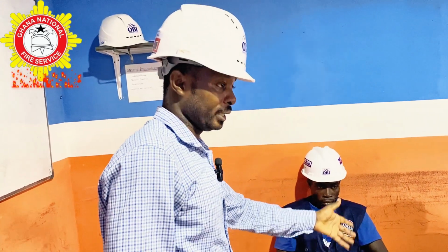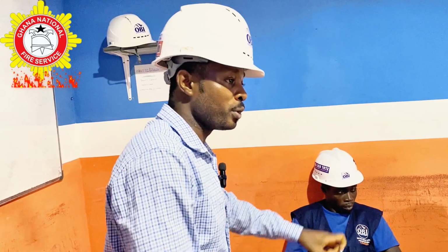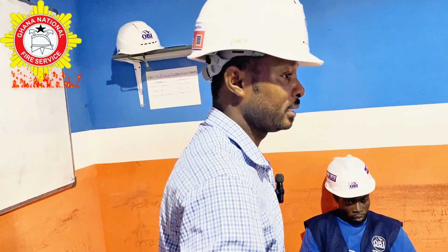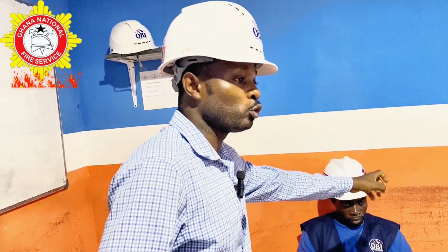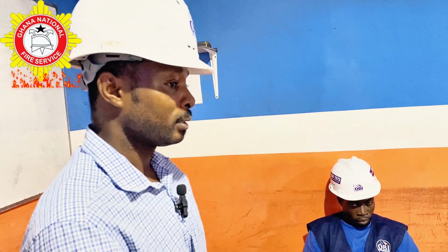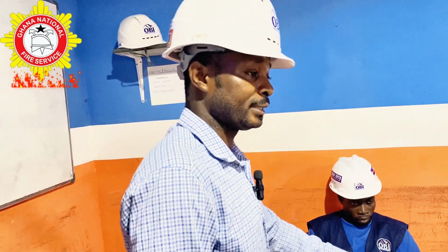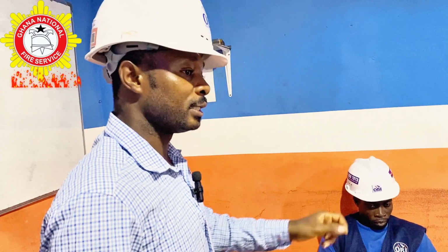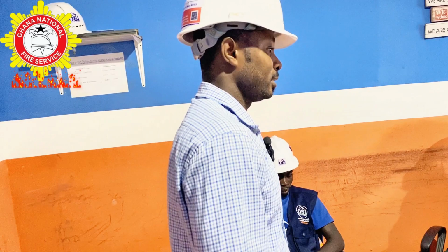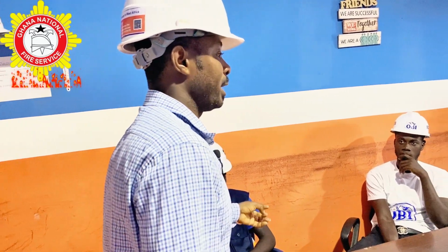Some are better than others, but because of the wire within it, the iron needs a lot of energy, so it will draw more current through the extension board than from the wall socket. And the extension board cannot take that current that the iron needs to work. So automatically it will start heating up and it is burning.